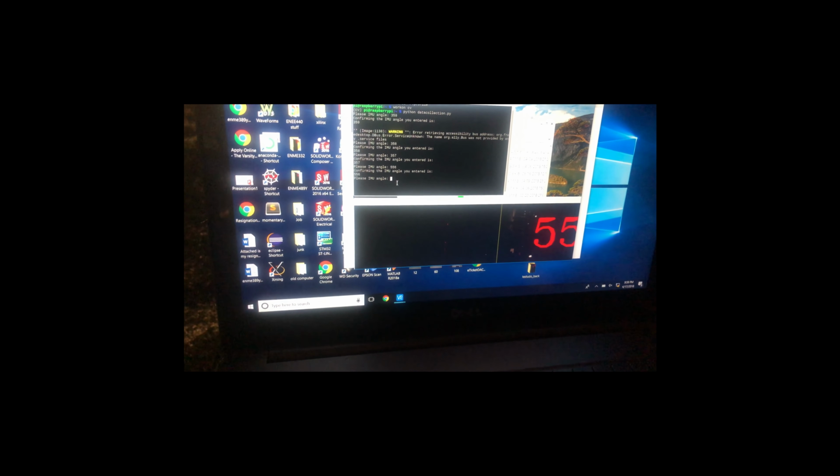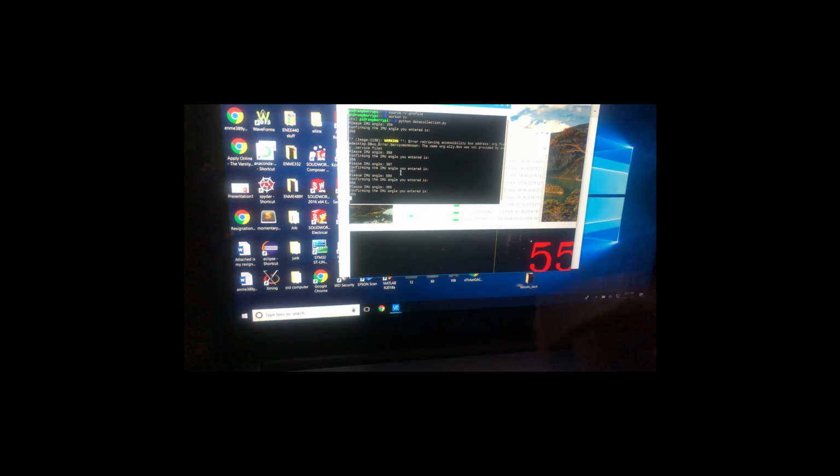See the line down here where I tried to get laser points. I wasn't getting anything. I'm out here mapping Testudo, and I've already begun. I wasn't really getting any returns off Testudo's top surface, so I had to put a bunch of flour on it. So you can see here, I just put 3, 5, 5, enter. So we can get some returns. It's kind of light, but we're still getting something. We can filter out later.